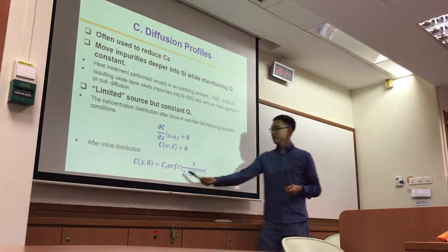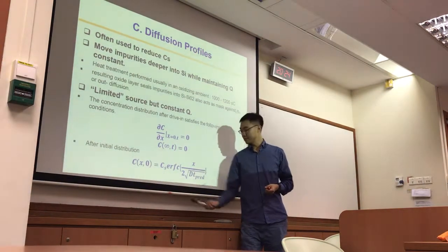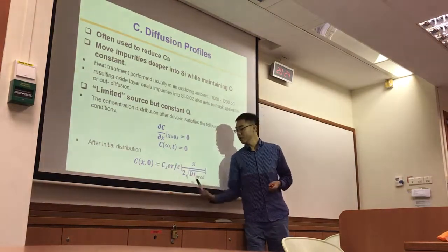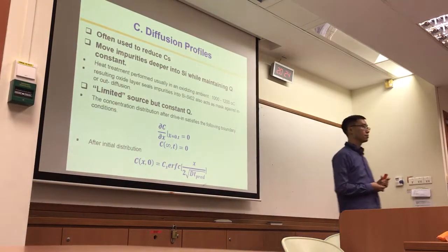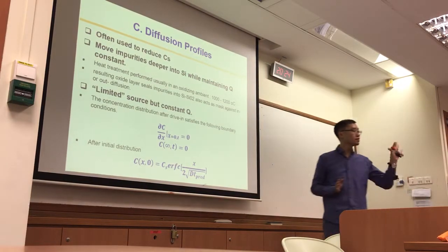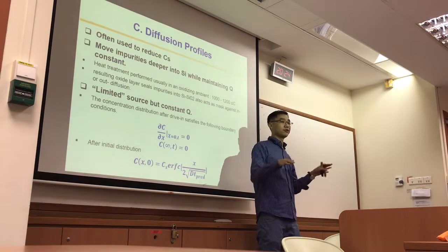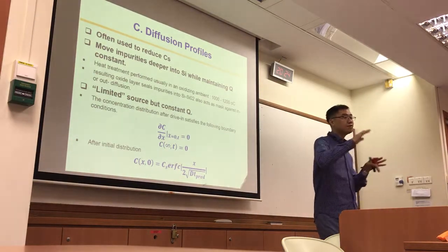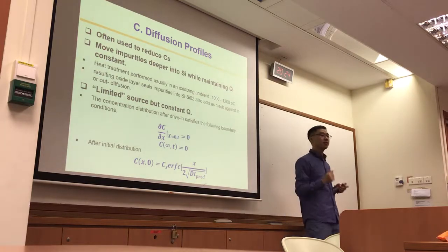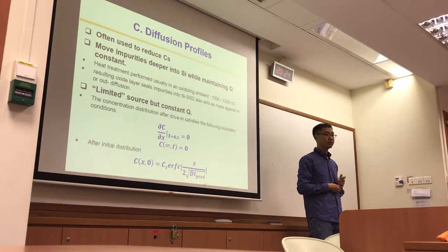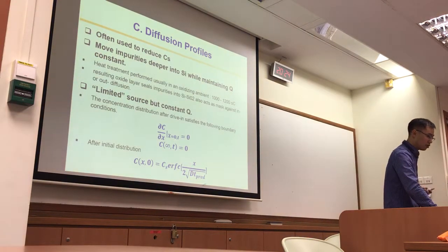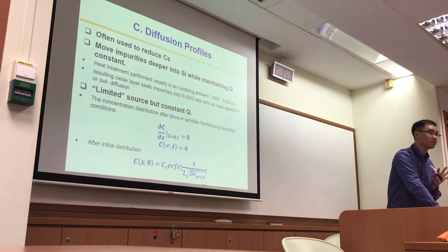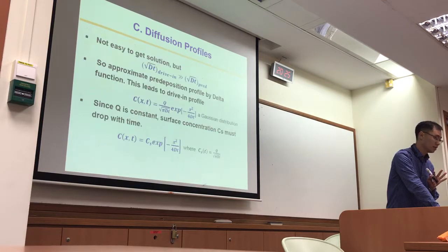Actually, this one, you see, the starting of this is the same as the pre-deposition. That's why when you calculate this, you have to use the pre-deposition time in order to calculate the concentration when you start the diffusion. Because diffusion is when you start the driving, and driving is done right after the pre-deposition. Correct? So here is the dose. Q here is also the dose.